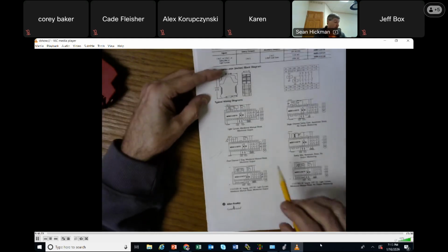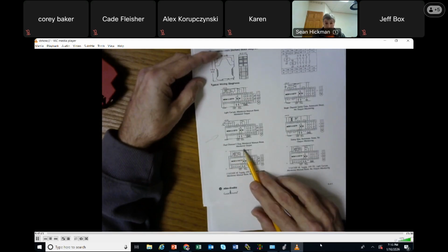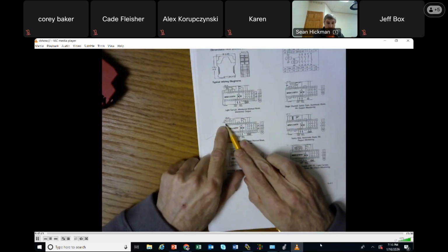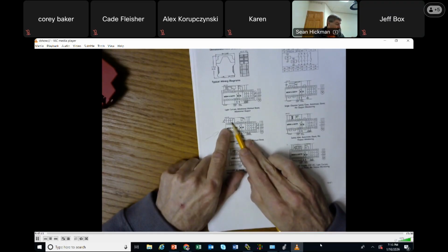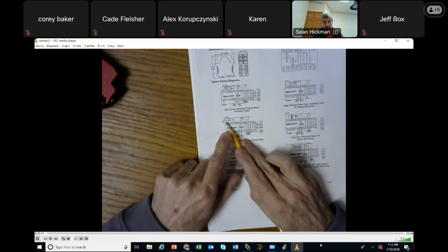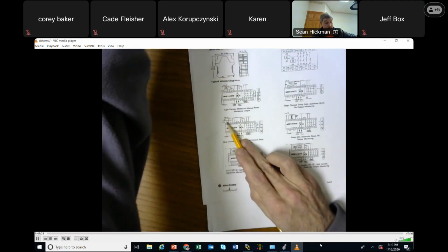So we're going to start with this one right here, a dual channel e-stop, monitor, manual reset, monitor output. And if you look up here, it says e-stop. The e-stop is showing one contact wrapped around to S11, S12, and a second contact wrapped around to S21, S22. That's an e-stop.